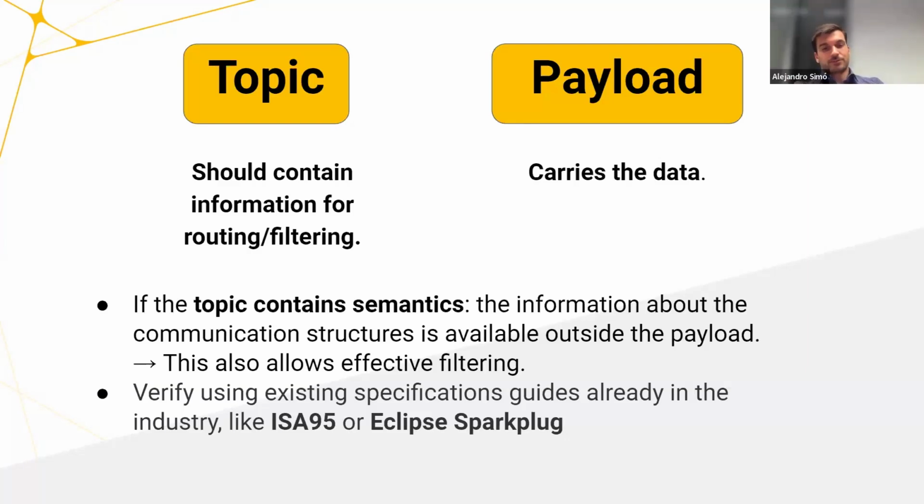Yeah, I agree on that, and I would also add that Sparkplug sometimes adds complexity that might be difficult to manage. Sparkplug also defines a very rigid topic hierarchy and topic guidelines. That's a major complaint about Eclipse Sparkplug that makes it really complicated, because of this rigidly defined topic structure. But we do have the two namespaces coexisting in the previous example that I was sharing before, actually.